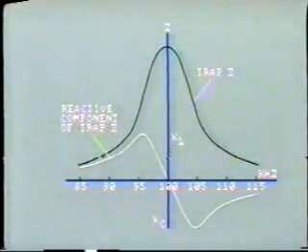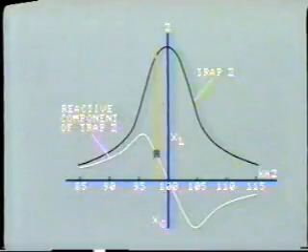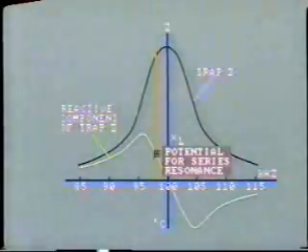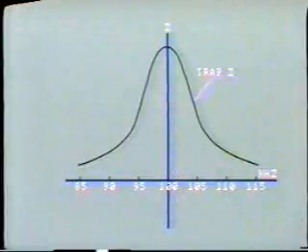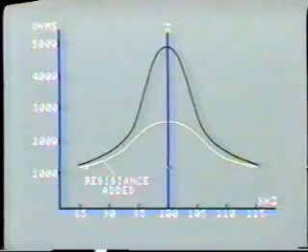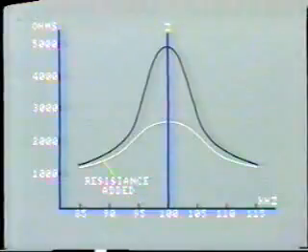From this curve, we can see that a small frequency change from 100 to 98 kilohertz will produce a highly inductive component with the consequent potential for series resonance with bus equipment. In order to avoid this potential problem, further resistance is added to the line trap. This actually has the effect of reducing the impedance at the resonant frequency, but improves the off-frequency operation by providing